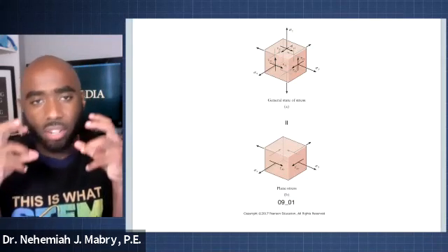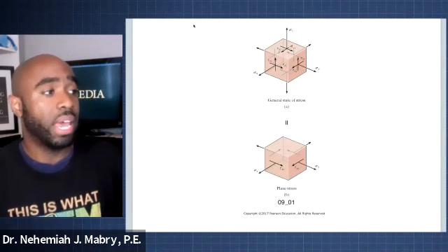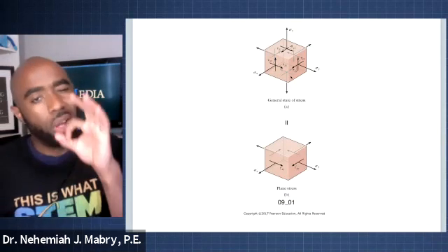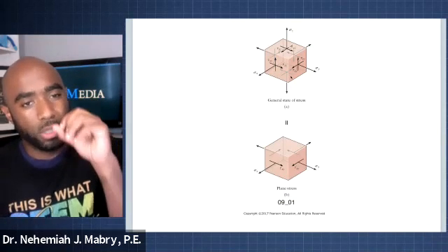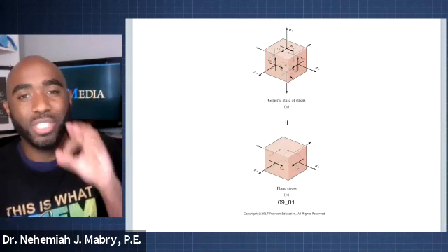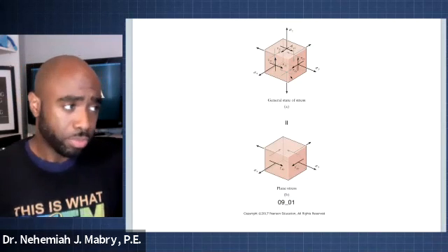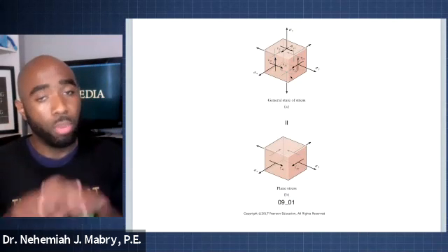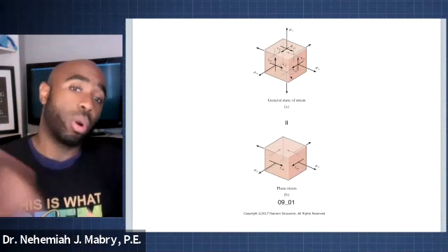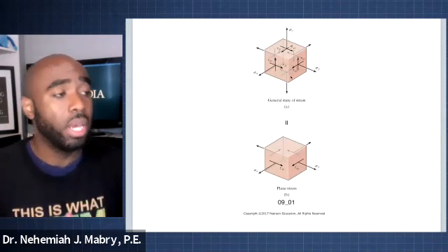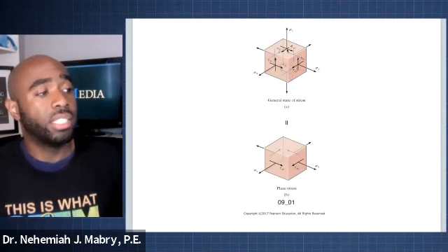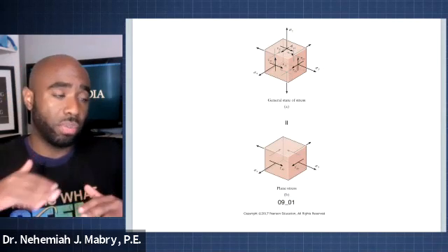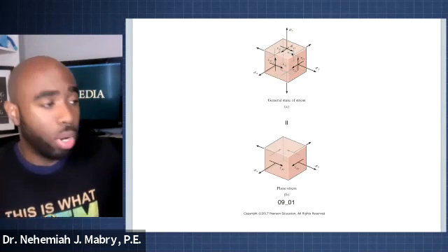So when we think about it from a 3D state, what we are able to simplify and understand as engineers is that if you took a cube, and we call this cube delta A, a small sectional area of our material, each surface of this three-dimensional cube portion of our material has a normal stress, which is perpendicular to it.